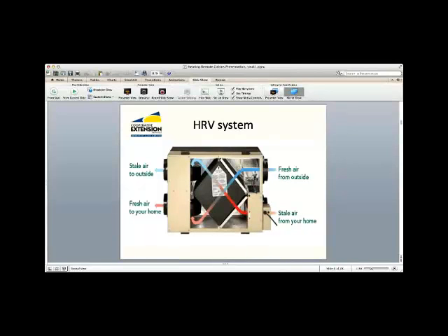The problem with the heat recovery ventilation system is that it's designed with some fairly sophisticated controls that require regular 110 outlet type of electricity on a continual basis. And what often happens then is that the electricity, if you're on a generator, needs to run constant. And with generators, we have brownouts. There are times where we turn a generator off because we don't want to waste the fuel and such.